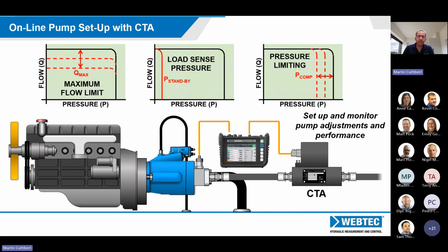On the CTA, if I understand the question correctly, the temperature is measuring the oil temperature. That is buried in the bottom of the flow transducer. As the oil goes across the bottom of that transducer, it is heating up that temperature sensor, so you're getting a very authentic oil temperature measurement out. But as I mentioned, you're only getting that signal using the CAN bus. The 4 to 20 milliamp only has a single signal coming out of it, and that's just the flow signal.